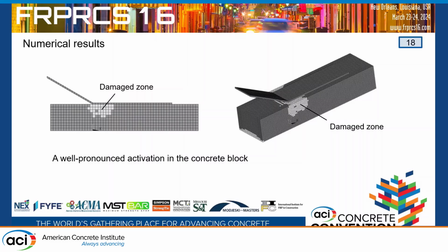These are finite elements in which some value of the damage variable, for example 0.3, is reached. The critical value of the damage variable should be defined. The critical value corresponds to failure of the element, and the corresponding finite element does not contribute to the overall stiffness of the system. So you have a rupture there. The debonding zone is already ruptured? No, this is damage in concrete. Only concrete, not the adhesive?